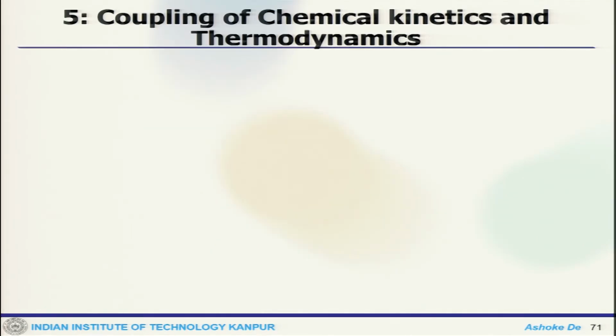So, again the mass conservation for any arbitrary species, one can write dm_i/dt equals omega dot_i times molecular weight times V plus m dot_i in minus m dot_i out.